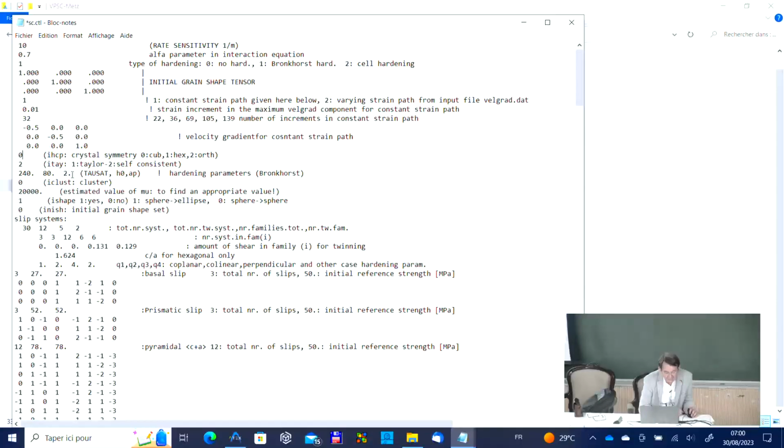Here we have hardening parameters, which I don't remember, but perhaps one of you was working out nice parameters. Do you remember? You know, tau sat. The tau saturation will be 142.5. And X naught will be 296. And the exponent? It will be 1.035. Okay. And then,